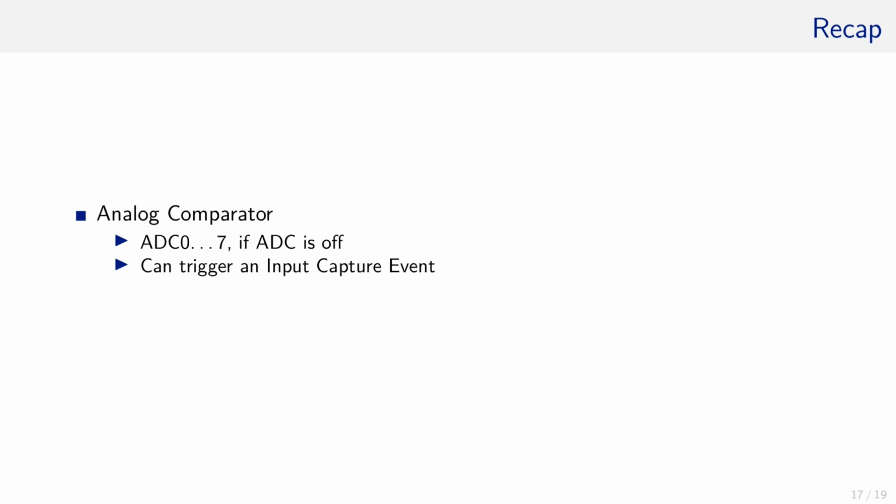If the ADC is not used, we can even use its analog inputs. Hence, with AIN0 and 1, we have 8 external channels available, or 10 channels if we consider alternative packagings, which have the channels ADC0 to ADC7 available instead of ADC0 to ADC5 only.